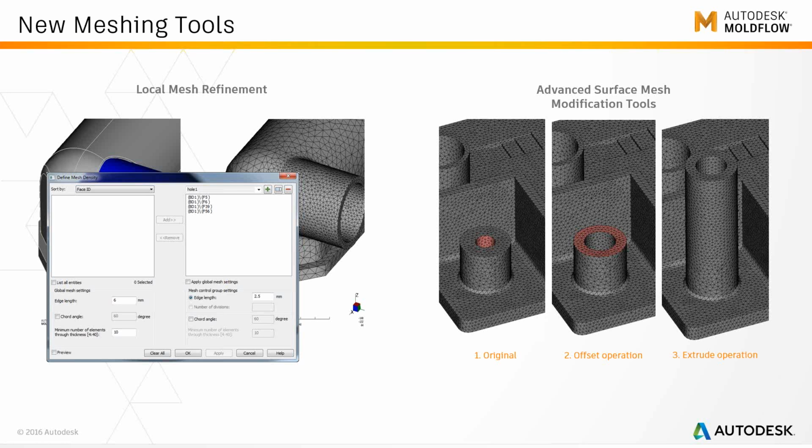We have some other work in progress on the CAD model to modify CAD faces and such, but that's not ready for prime time just yet. So this works on surface mesh, not on a 3D mesh. If you wanted to do this on a 3D mesh, you have to strip the model back down to a surface mesh, make the design changes you want, and create a tet mesh from that again.